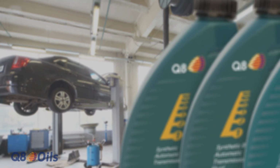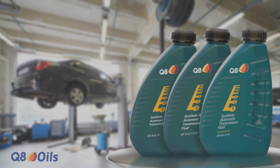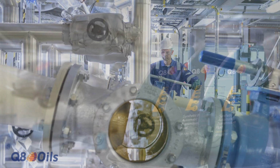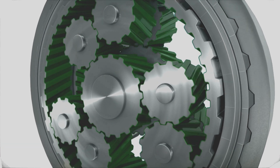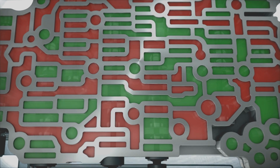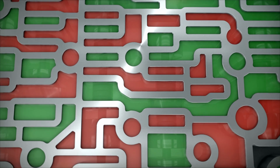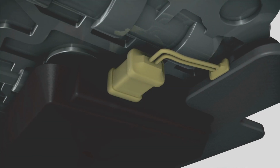The one component of the entire system that's critical to all these parts working together is the automatic transmission fluid, or ATF. Every ATF is a precise blend of different chemicals because it has to do a lot of different jobs. It acts as a hydraulic fluid to engage clutch packs and shift the gears. It acts as a corrosion inhibitor and wear protection for the planetary gear sets. It has to flow easily from -40 degrees Celsius to over 200, even in fine valve assemblies.